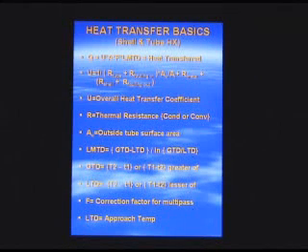So we take 1 divided by the resistances. This would be the inside tube resistance, which would be based on an inside heat transfer coefficient, 1 over that coefficient.